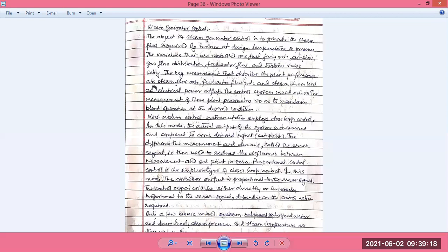And how much gas flow distribution, how much gas flows in different directions after the burning, how much it is used to heat the fluid going through the enormous number of riser tubes inside the wall, and how we will distribute the heat, in which portion it will heat more, which portion will heat less, and how we will control this distribution of heat, either by providing a wall or by providing different types of steam at different intervals of time, so that one type is usable at one moment and another type is usable at some other moment. Now, the key measurement is described.